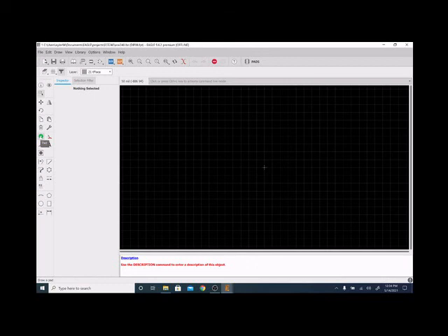All right, so I'm going to go to the pad tool to make these pads. And you can see right now it gives me a square pad. That's fine if I wanted to. I'm going to go for this offset pad just because it gives me a little more room to solder to, but really this depends on what you're using. Sometimes people will use an octagonal one to identify the ground pin. They might create a square one instead. They might use circular if they're trying to make things nice and tight. Or you might use an offset if you were trying to solder a wire onto your board and you want a lot of extra space only in one direction.